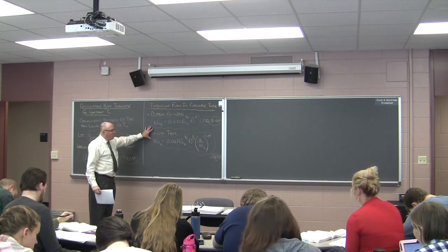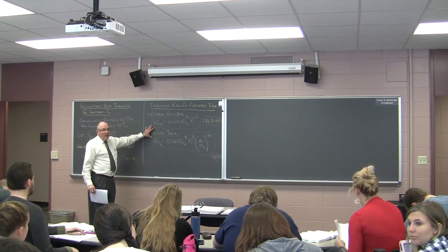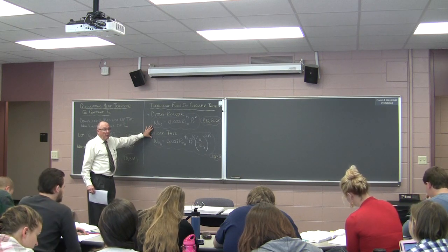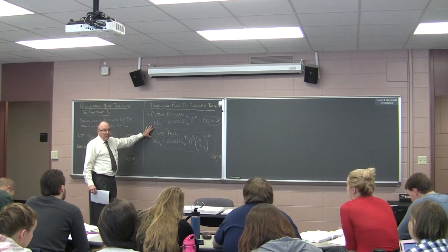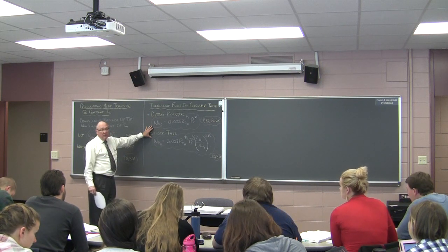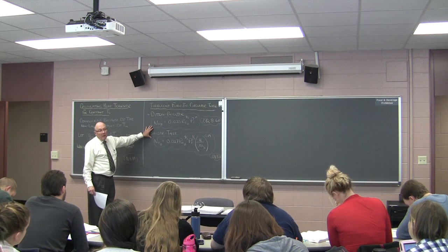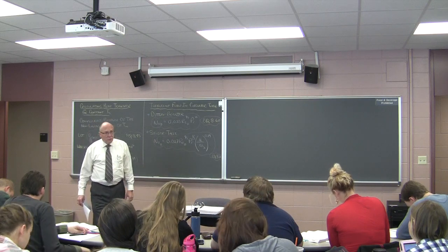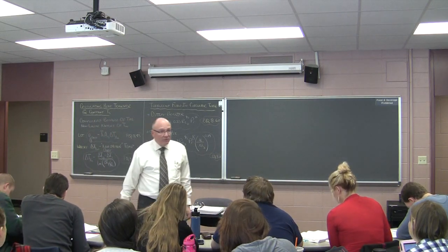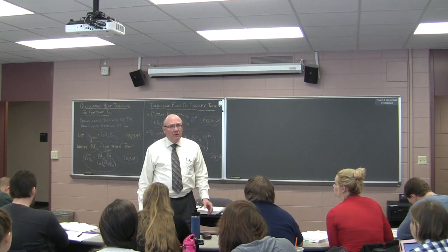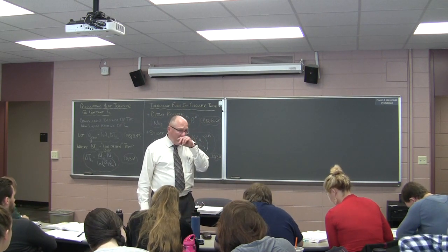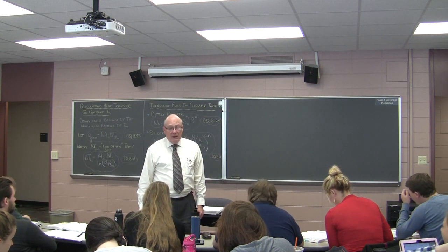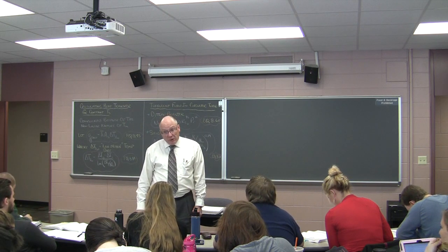All right, these are the two equations that you're going to use to solve for the h value. And what are you going to do when you have a problem? The first thing you're going to do when you encounter a pipe flow problem is what? Dylan? Do the Reynolds number. If the Reynolds number is greater than 2300, yeah. Now, if it's really turbulent, how far do you think the entry region is? Really small. Very, very teeny. The bigger the Reynolds number, the smaller the entry region. If you have a Reynolds number of 3,000, 4,000, in practical terms, you probably should calculate the entry region as well, because it may be pretty long.